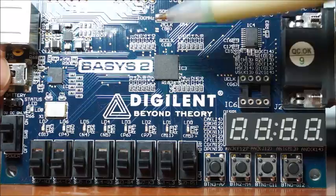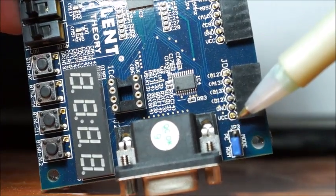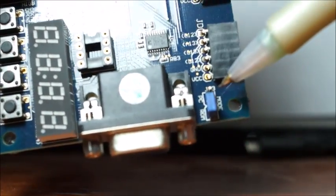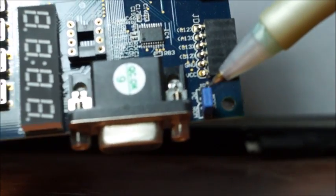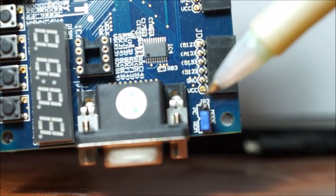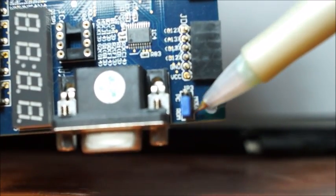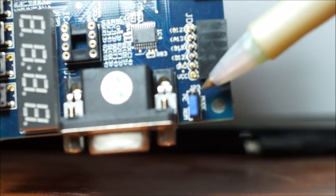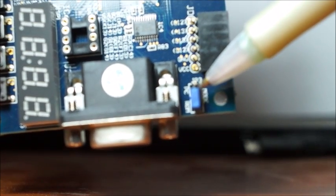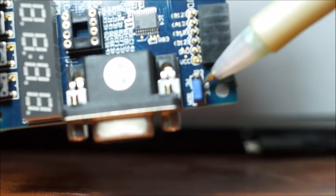Along with these, you also get this jumper right here. This jumper is used to switch between PC and EEPROM mode. So if you write your code to the EEPROM that's on board the FPGA, you want to make sure that this jumper is set to EEPROM mode. That way your program will run no matter how it is connected. Even if it's connected off an independent power supply, your program should still run without any USB connection.